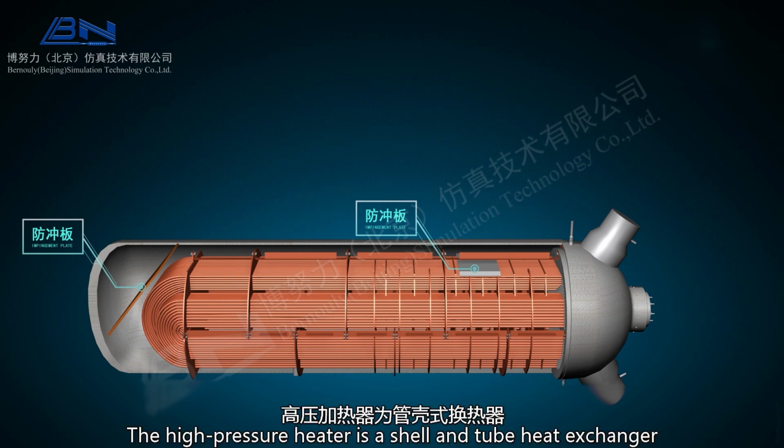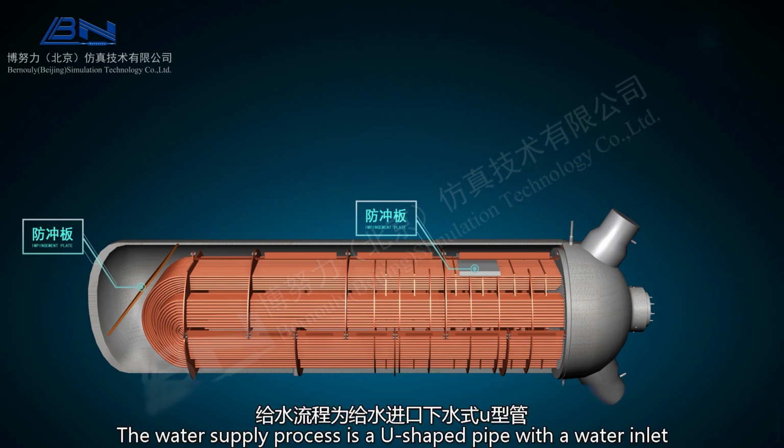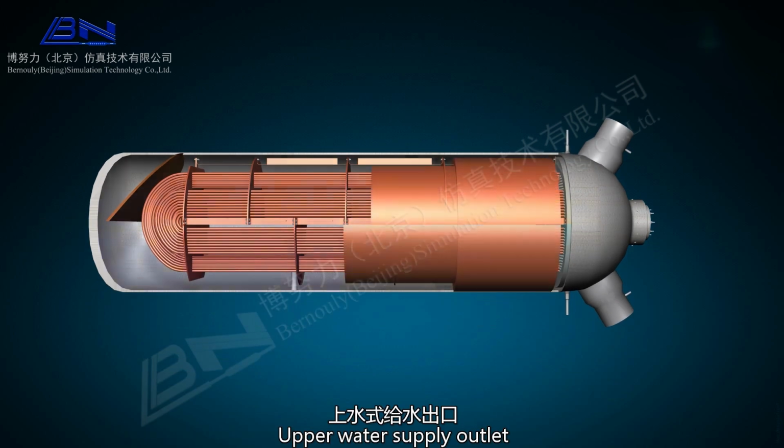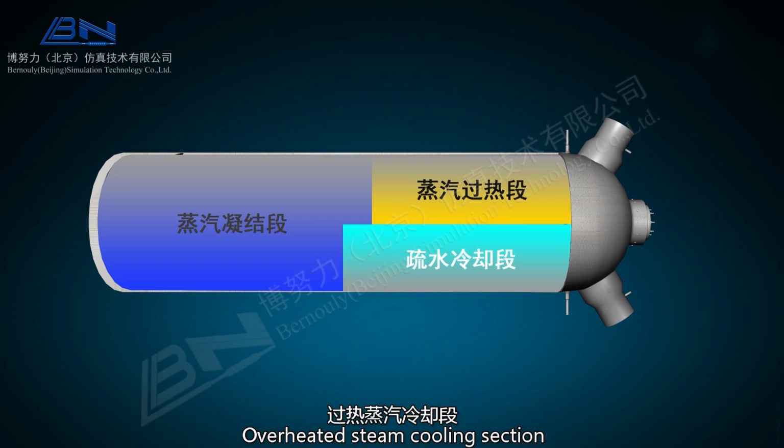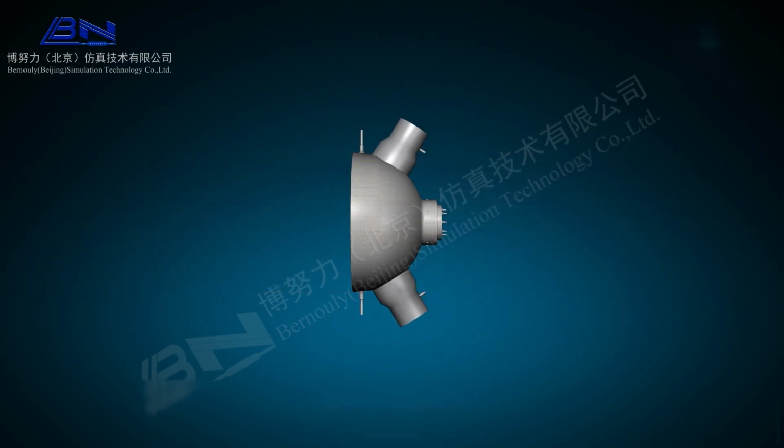The workflow of the high pressure heater is as follows. The high pressure heater is a shell and tube heat exchanger. When the high pressure heater is working, the water supply flows in through the water inlet, through the U-shaped pipe, to the upper water supply outlet. Three heat transfer sections are set on the steam side: the superheated steam cooling section, the condensation section, and the drain cooling section.